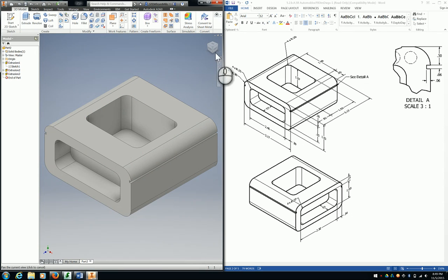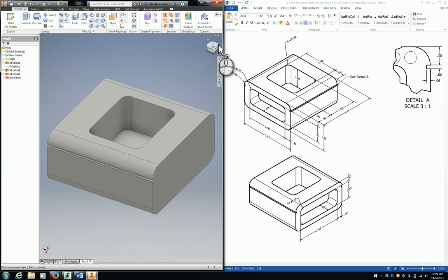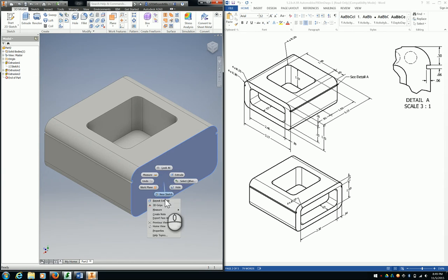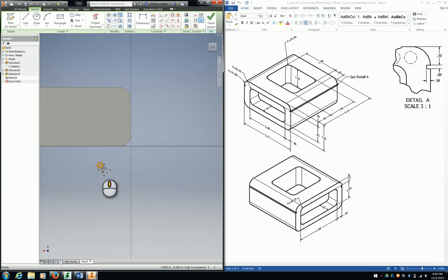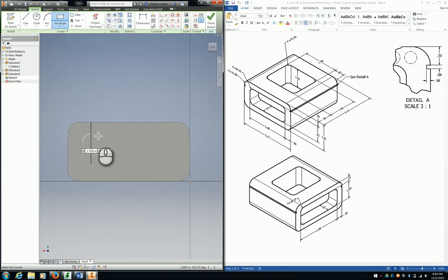Finally, we're going to get the back side. Navigation cube to see here. We're going to do a new sketch on this one. And same process. Again, a lot of different things that it's picked up in the background now. Again, it's seeing those sorts of things from last time. So again, I actually don't like that. I just kind of want to click anywhere. And once again, I'm going to dimension it, I'm going to locate it, fillet it, and extrude. So let's get underway.